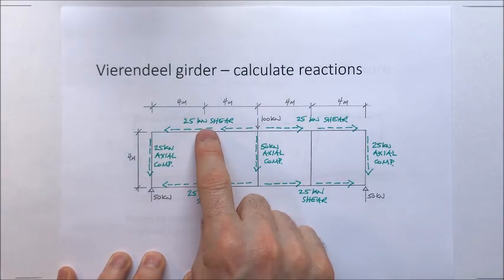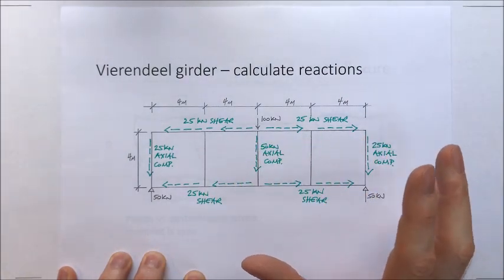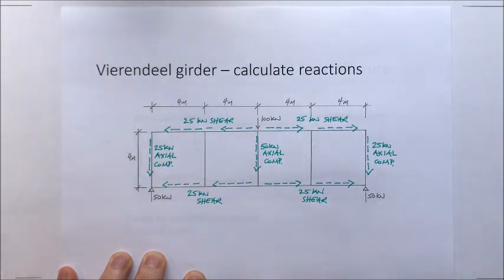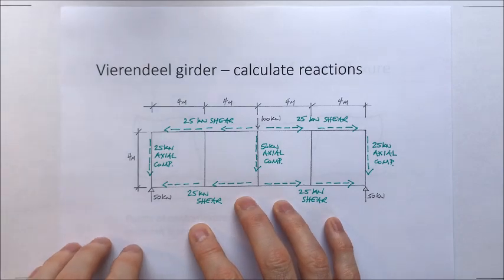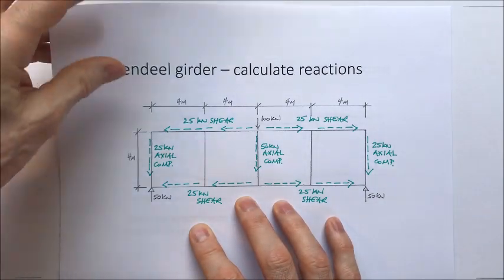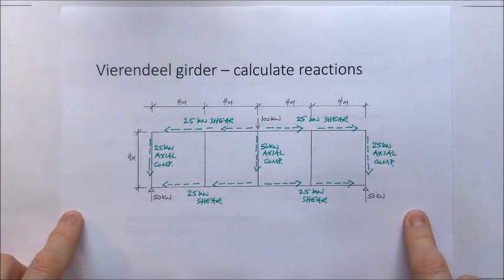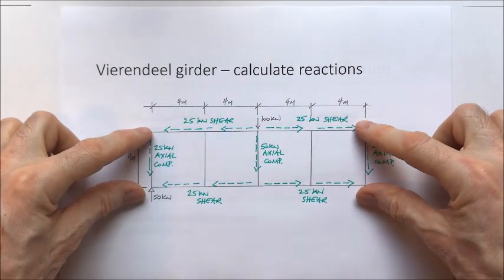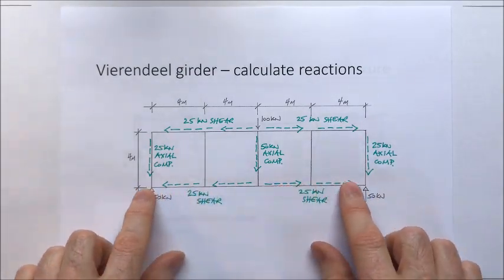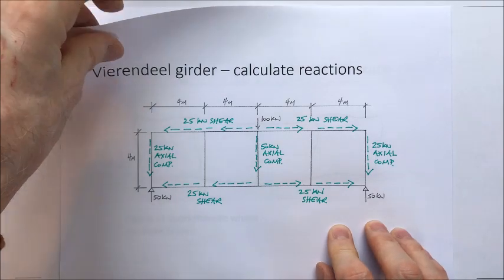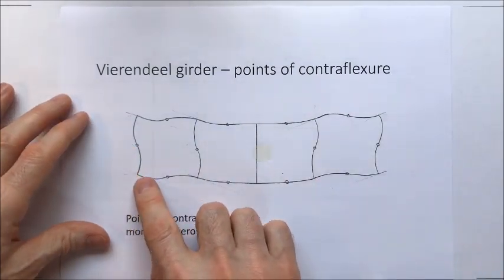Yes, there are axial forces within all of these members which are of interest, but the forces that I'm really interested in for this analysis are the shear forces that are transmitted along the members, which create significant bending moments within the members, and particularly at the joints. So you can see that there's a kind of equals approach here. This 100 kilonewtons is shared out both sides equally, and it's shared out top and bottom equally. So that means that I've got this 25 kilonewtons shear, 25 kilonewtons axial compression, and 25 kilonewtons shear. Okay, that's important to have a feel for the way that the forces flow through the structure, especially when you're as good at drawing deflected shapes as I am.